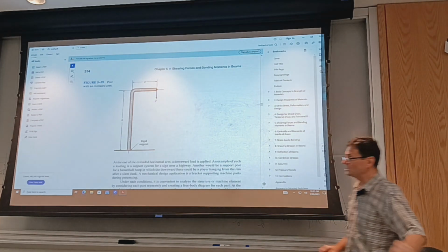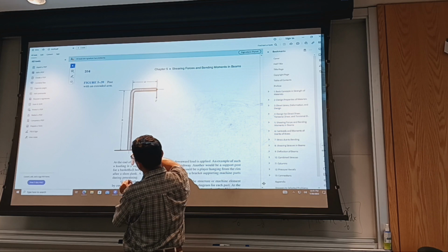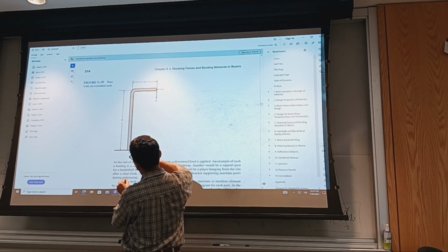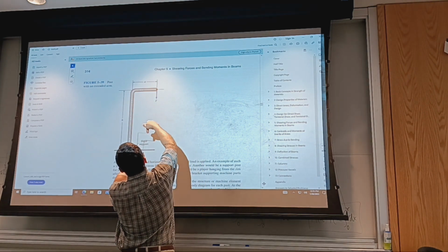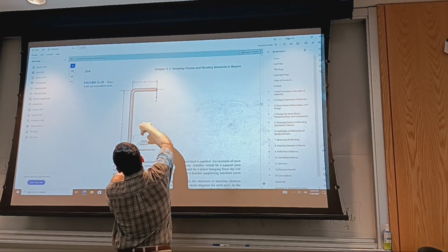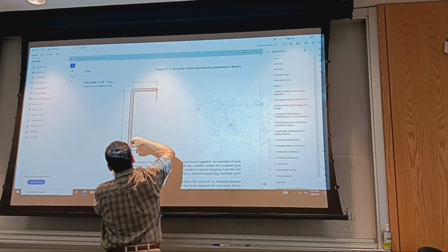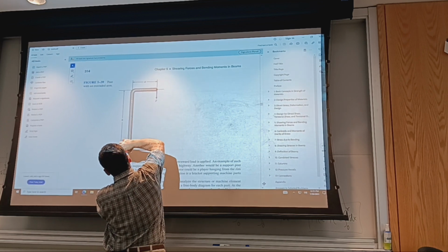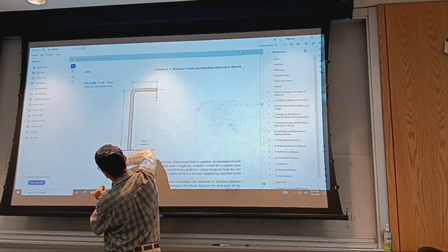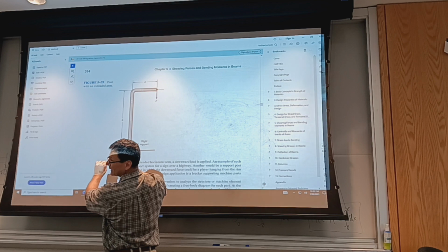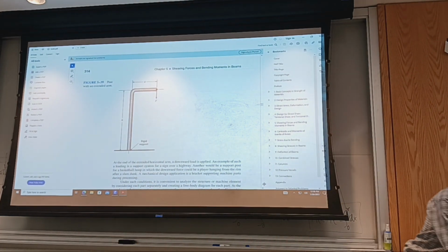Again, the moments transmit at bends. Forces may turn from bending force to compressive force. So as I move this force here to capture the effect of the offset, I get the compressive force and the moment at the end. This beam is subject to a moment, like a cantilever with a moment at the end only, and the compressive force.